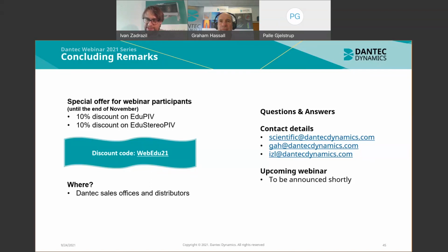If we look, for example, at the spatial resolution, it is the highest for CTA, slightly lower for LDA, and considerably lower for PIV. So for CTA, you get more detailed information about the flow structure. But temporal resolution is also different. CTA has the highest temporal resolution; you can acquire up to 400 kilohertz. Then you have LDA, about 100 kilohertz, and PIV, where acquiring at 1 kilohertz is already a challenge. So you get more temporal information about the flow with the point techniques.